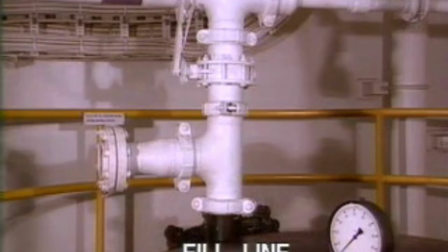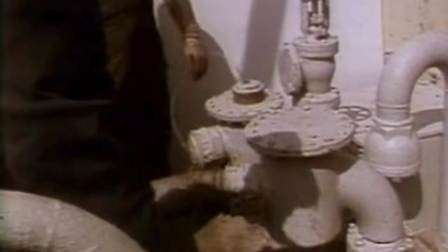The fill line is used to fill the tanks. This is the line that bulk is transferred through to its destination. They originate at the port and starboard sides of the rig. This is the connection that supply boats hook into to offload bulk materials, products like bentonite, barite, and cement. As a derrick man, you'll probably never have to deal with the offloading operation, but you need to be aware that this operation occurs. Whenever a P-tank is being loaded from a supply boat, it can't be used for transferring materials.